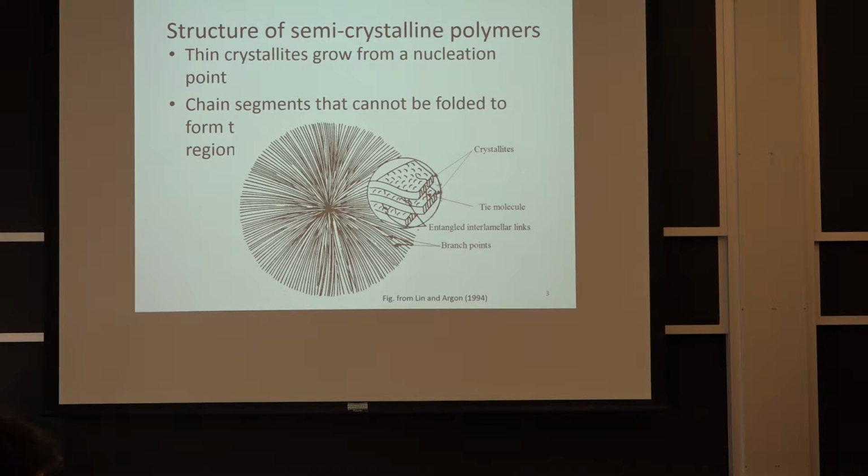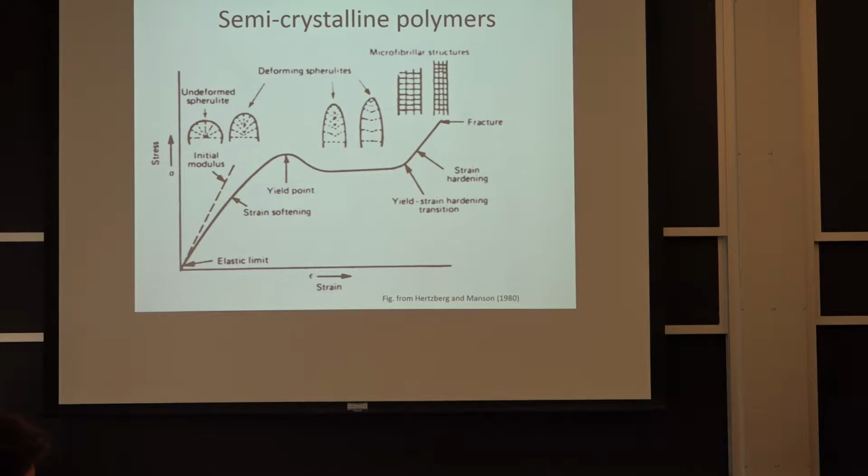It does affect a lot the mechanical behavior, and that's why when we take a nylon cord, it's a lot stronger, because you've broken down by deformation that cast structure, and everything now is a lot more organized. If you have an injection molded part, then it is a lot softer. So your strength can be just of the order of 1/3 the strength that you'll have from the cord.